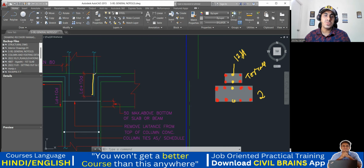So this clause will tell us how it has to be done. You can see this bar they took, and it will be stopped here. That means all this bar will be stopped. This bar, this bar, this bar will be stopped. And if you want to put additional steel, you bring the additional steel and insert it into your column, but it has to go up to LD plus 10D.